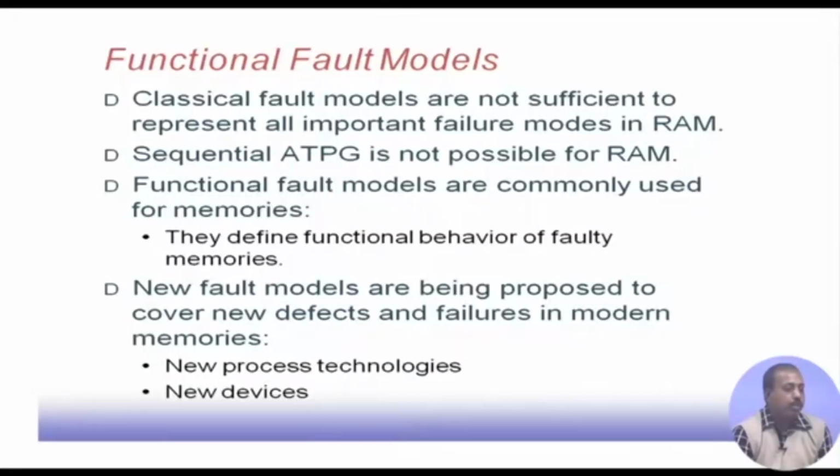Now, the functional fault models that we have for RAM are significantly different from the classical fault models that we have for logic circuits. Classical fault models are not sufficient to represent all important failure modes in RAM. Sequential ATPG is not possible for RAM, because there is a huge number of cells. If you try to do sequential ATPG and model every cell as a flip flop or latch, it is a huge number of flip flops, so it is not possible.